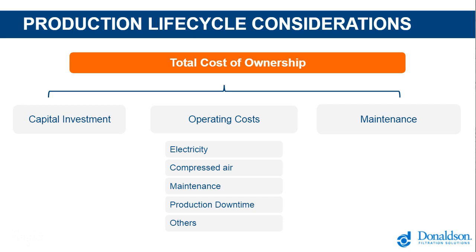But from an operational point of view, proper maintenance will help you keep a lot of cost drivers under control. For instance, your electrical consumption, because the higher your pressure drop is, the higher the energy need for dust extraction. Your compressed air usage: not well-maintained systems will simply require more compressed air, and they will require higher pressures, plus a higher frequency to clean your filtration elements. But it's not only that. You can also think about factors such as product quality and cleanliness of operation. All of these are influenced by maintenance actions.